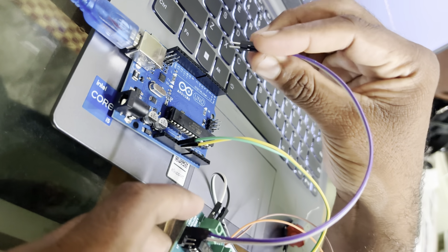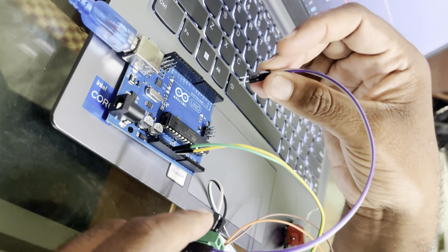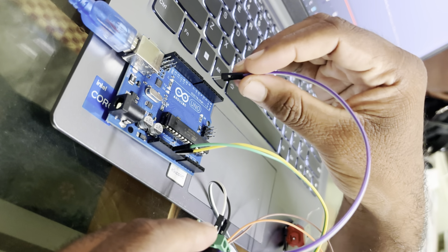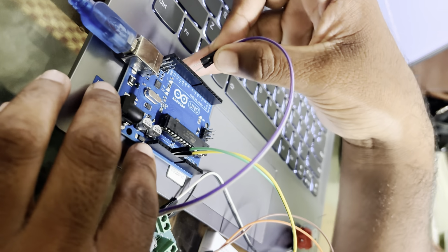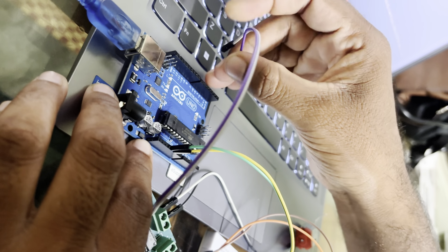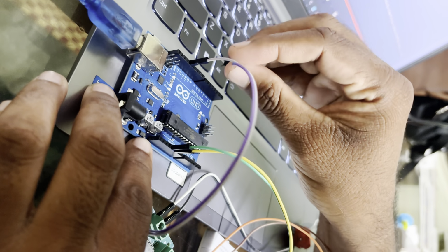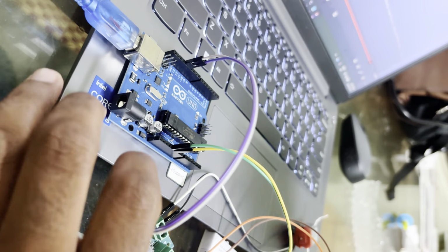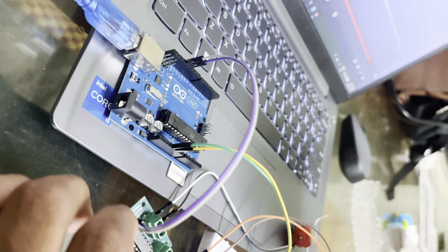B4 and B5 connections of the AVR microcontroller. Here in the Arduino development board, as we know, the 13th pin is B5 and the 12th pin is B4. Now I am going to connect the 13th pin and the 12th pin. First you can connect the 13th pin, then I am going to connect the 12th pin, from the microcontroller to the motor driver.